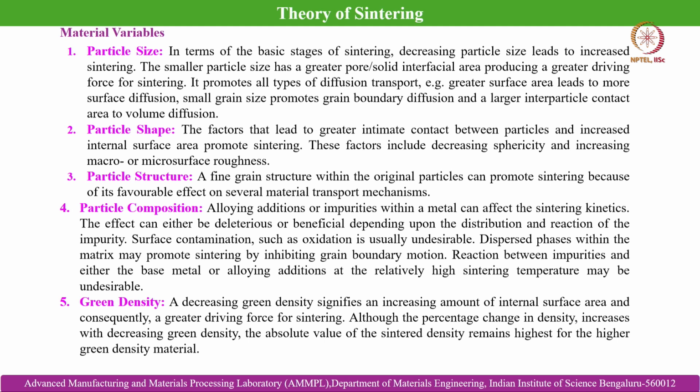So, the material variables. We have talked about process variables until now. Let us focus on the material variables now, because they also play a pivotal role in determining the success of the sintering process. So, the particle size: in terms of the basic stages of sintering, decreasing particle size leads to increased sintering, a higher sintering rate.